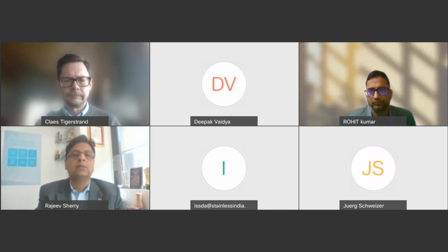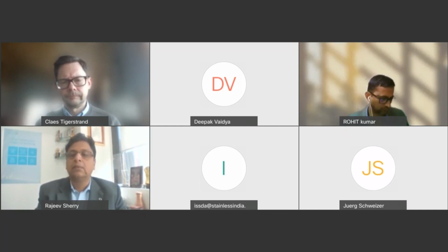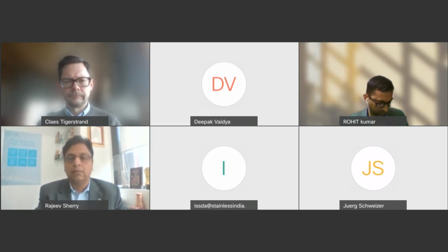If you talk about the corrosion resistance, which you have mentioned, for 301 LN, normally the PREN number is around 20. But if you talk about the lean duplex LDX 2101, which is 26 PREN, it means you get a higher corrosion resistance and you get higher strength also. That's the brief answer to your question.